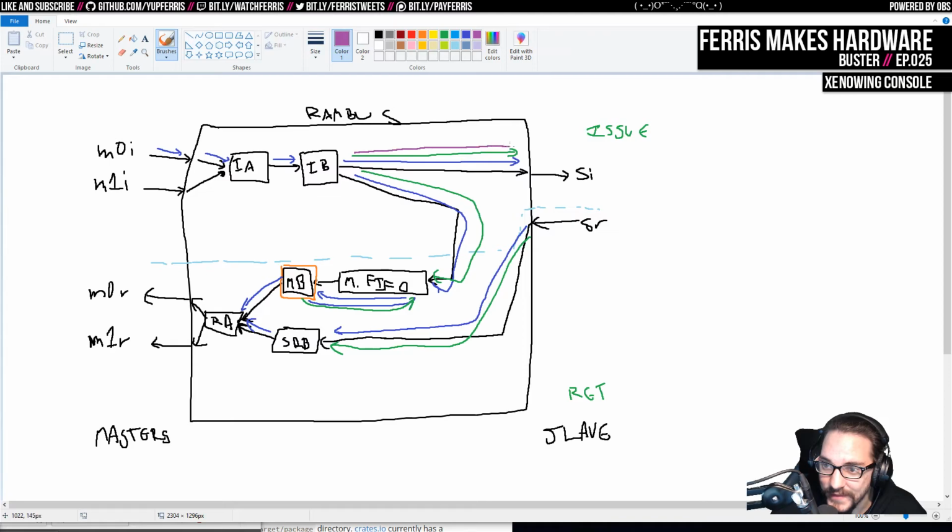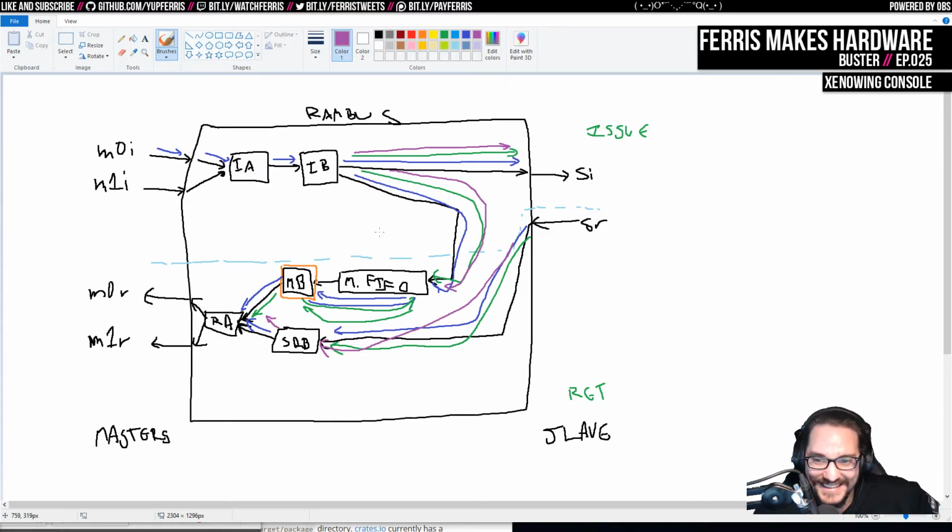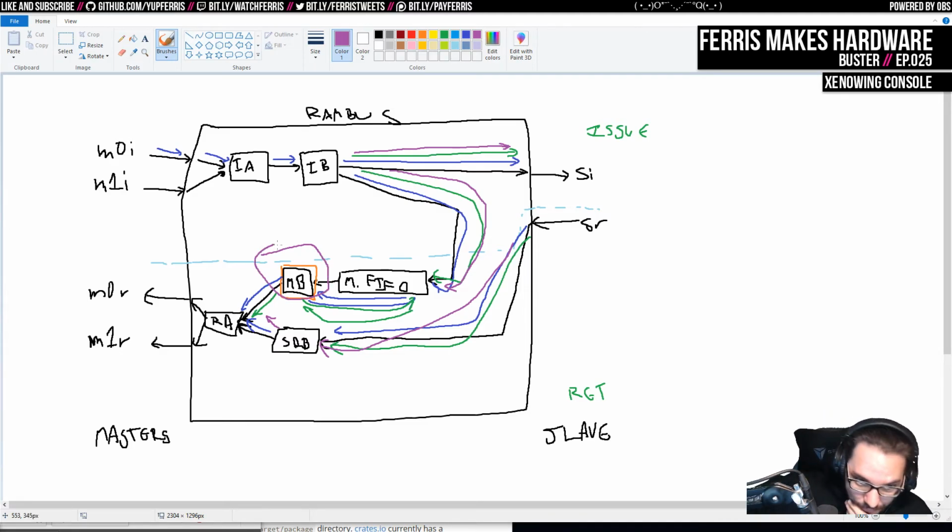It's maybe purple. Because then on the following cycle, this data comes in and this data comes in. And then we've lost data. Because on the following cycle after that, this is going to read green from here and purple from here. Okay, this design's not sufficient. There's a bottleneck in how this buffering works that I need to think through. This would have come up in testing. I don't know if I'm lucky or unlucky that I thought of it now.